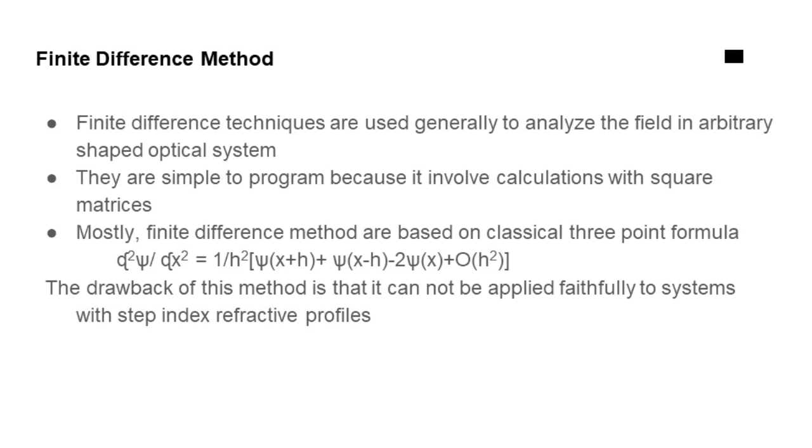It is then usually recommended that discontinuities be placed halfway between constitutive sampling points, or that the exact permittivity on every grid point x be replaced with its average on the corresponding mesh. When the refractive index is discontinuous and the second derivative is continuous, this classical 3-point formula contains a zero order error. Many researchers have been studying different waveguide problems using this finite difference technique.